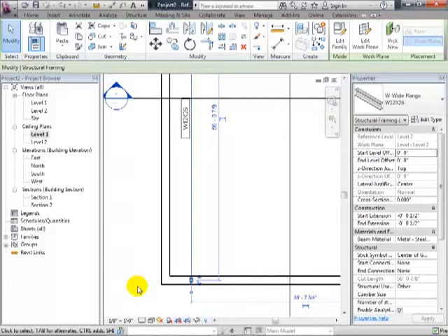Oh, all right, so let's go back and see what's going on. So, did you turn on visibility graphics? Yeah. Oh my God, actually, we do think it's there. It may be very, oh, you know what, do this for a minute for me. Go to here, right next to it, and turn on wire. Okay. I think what's going on is your 2x8 is so small it's buried alive inside the floor. We're going to fix that in just a second. Oh, okay. What's happening is if you have a hidden line view and your structural framing element's relatively small, it may be buried alive inside the sandwich of the floor.